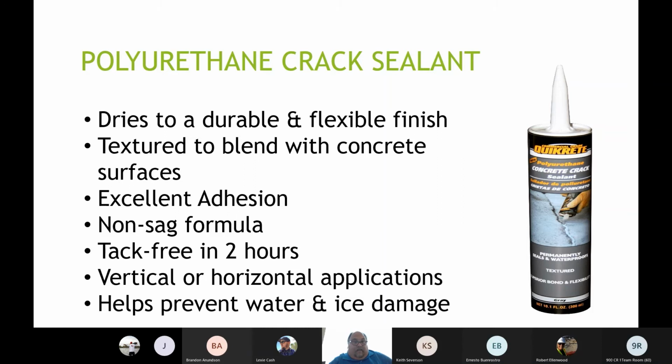So if you're thinking about one day I might want to do that, make sure you use something with the cement base, something cementitious like the vinyl concrete patch or the facet repair mortar, so that way you can go over the top of it. If you are going over the top of it with the facet repair mortar, you can go over that in a day. The vinyl concrete patch, you need to wait about 7 days before we go over the top of it.